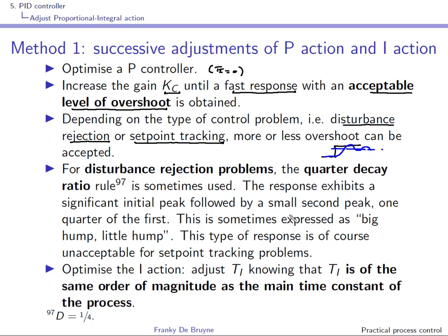And if it does, you can use the parameter b, smaller than 1 in that case, to reduce the proportional kick on MV, and it's that kick of MV that is producing this oscillation. If you use b smaller than 1, you count on the integral action to obtain PV equal to set point.